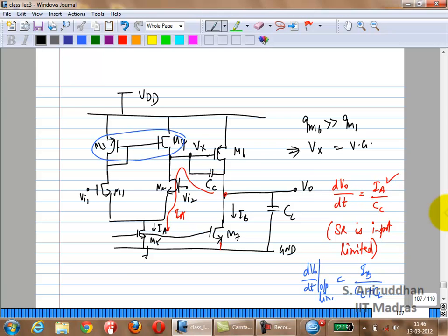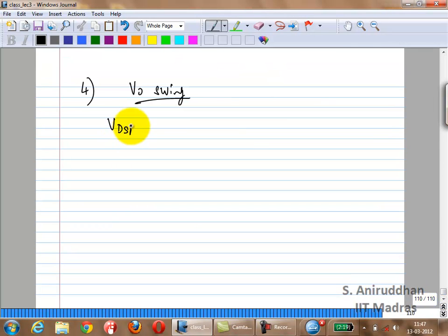Right? We'll do it this way. We'll just start off with VDSAT, see if it meets the condition. So we are going to say both sides have 0.5 volts. So based on this, IB, right? You can find out W over L of each one of these guys. Okay? So I'll give you the values. I want you to go back and check it.